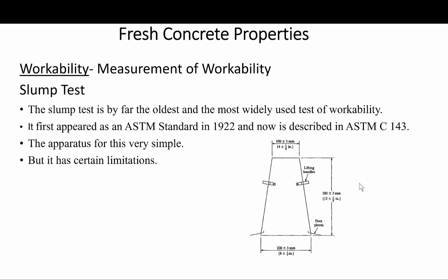Okay. So the maximum time from the first placement of concrete to lifting of the cone is 2.5 minutes. Also, if a distinct shearing off of concrete from one side occurs, then the test is regarded as invalid and a new test is carried out.